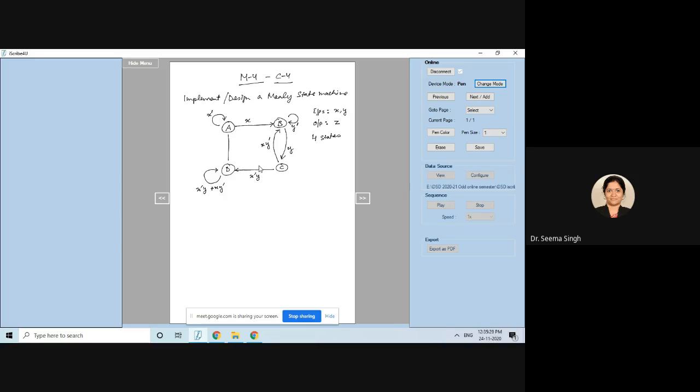Okay. Now last, I am showing you this. You will see so many arrows I made, but nowhere did I mention Z, right? In the previous class, I showed you that in the Mealy state machine notation, we put a slash here and then show Z. Now I will show you that condition. From D to A, the transition happens if X dash Y dash, that means X and Y both are 0, 0. State changes from D to A and the output is Z dash.